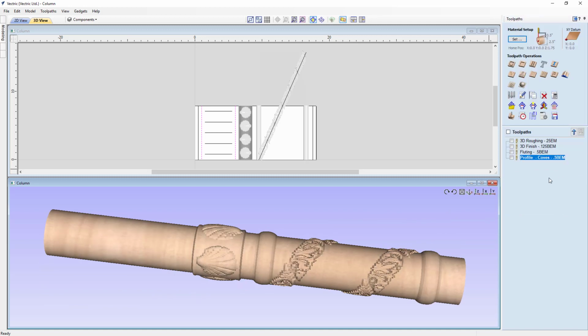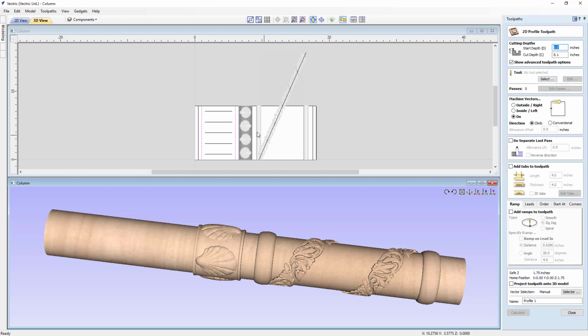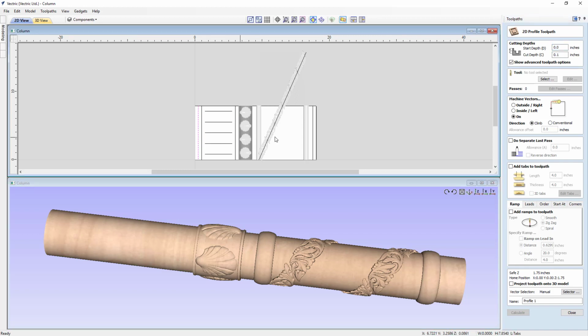And then for our last toolpath, we're actually going to cut the tabs. So this will make it easier for us to remove it. Once we pop our material off our machine, we'll know exactly where to cut. So to do that, we're going to use a profile cut again, but we're going to select these outside vectors. And we're going to start at the 0.2547 again.